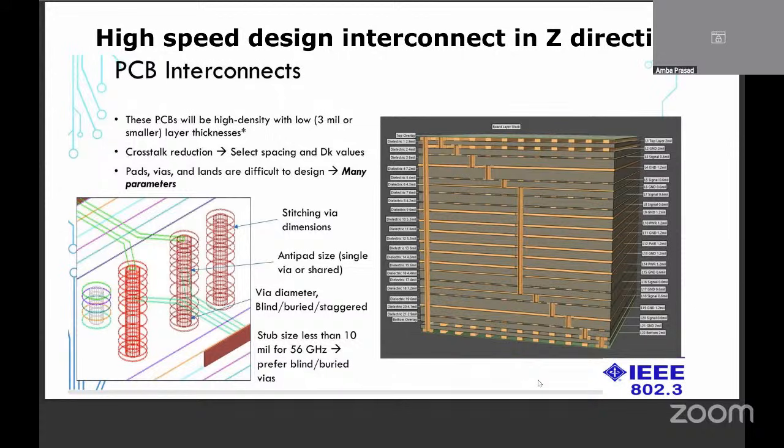And again, there is going to be some gap between what we have simulated and finally what we get manufactured at the PCB level, because the PCB itself has got some tolerances. So especially when we talk about 224 Gbps, even a tolerance of 0.05 millimeter can act like a discontinuity of a huge magnitude. So we should have a very tight budgeting and a very tight tolerancing. So the budgeting is CTF, tolerance is CTQ. Okay, great.